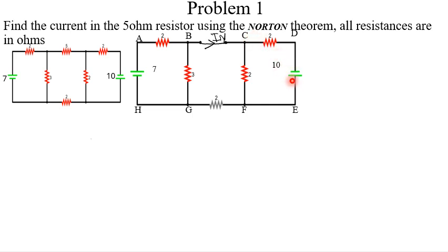This source also delivers a current. So let us name that source I2. That current, because the current will be entering, right? I2. And since that is I2, applying KCL at node C, we'll say sum of currents entering is equal to sum of currents leaving.